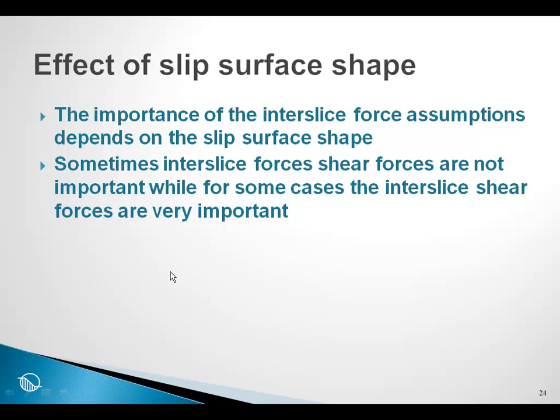The question often arises, how important is this assumption? As it turns out, the assumption we make depends on the shape of the slip surface that we are trying to analyze. Sometimes the interslice forces, particularly the shear forces, are not important, while for some cases the interslice shear forces are very important.